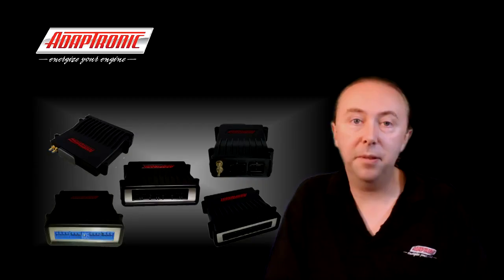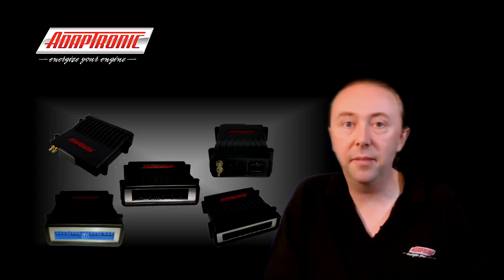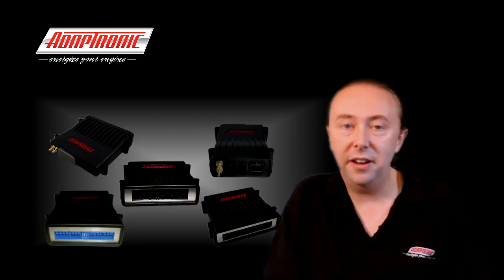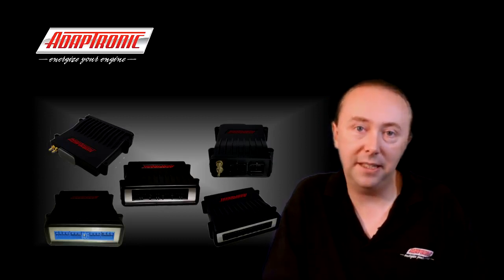Now, if you just want a simple threshold-based switch, like, for example, turning on an additional fuel pump when the MAP gets above 130 kPa, or 5 psi boost, then you do it the same way, except you'd need to set the off above setting to be a very high value so that it never gets triggered. For example, 400 kPa or 45 psi of boost.